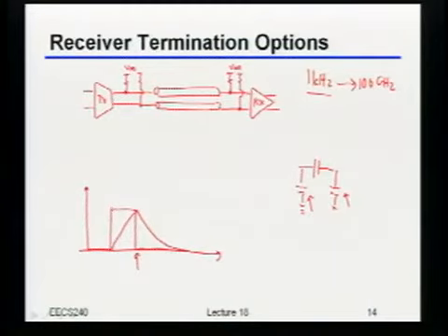Yeah, that's kind of like my longest sequence of bits that maybe I care about before I recalibrate or something. And by the way, even if I went down to like 1 second, remember, that's not going to have a huge impact on the flicker noise you pick up, right? Because there's only so many orders of magnitude between 1 kilohertz and 1 second, and there's a lot more orders of magnitude between 1 kilohertz and 100 gigahertz.